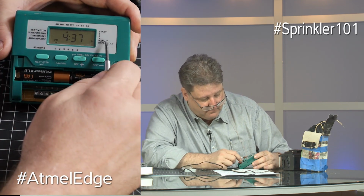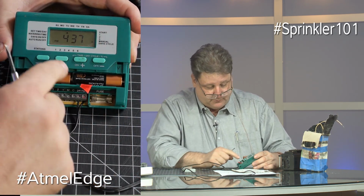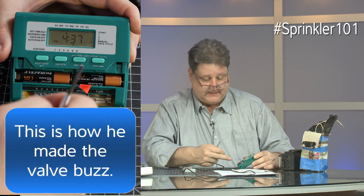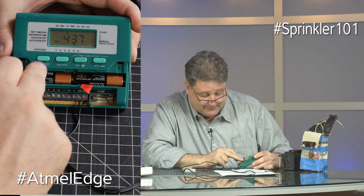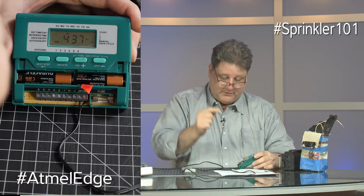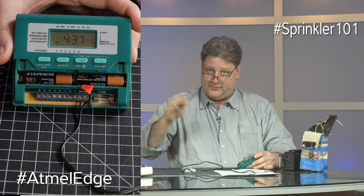Next step, manual. Also very confusing. There's 3 manuals. This is manual. It doesn't say P1 or 2. When you press the station, pick one of these stations, and it just rolls around. Hooray. Say on, that power goes to that station. Say off, it turns off. Now press next step again. Notice it says manual. It's got a little triangle by manual, but it says P1. Which means when you press on now, it runs that program. If you have 6 sprinklers going or 6 stations, whatever it is, it's going to go through that sequence.